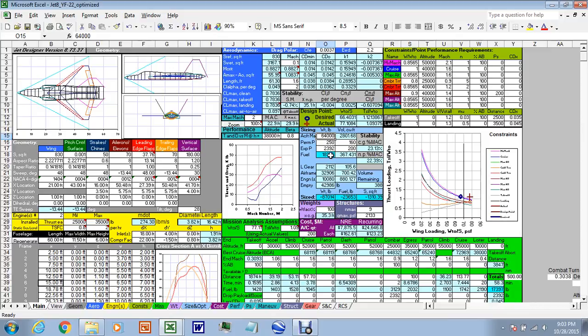What's left must be fuel, and so that's how the fuel quantity is calculated. That way we're controlling how much fuel we carry by typing in a number for the aircraft takeoff gross weight. So we've got too much gas, so we'll make the takeoff gross weight less, 63,000. And we still have a little bit more, 62.8, because that lighter airplane burned less gas on the mission.